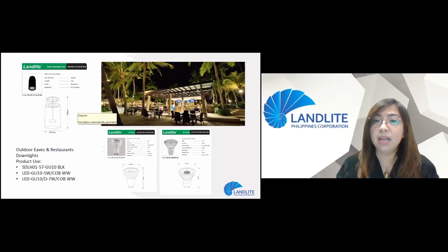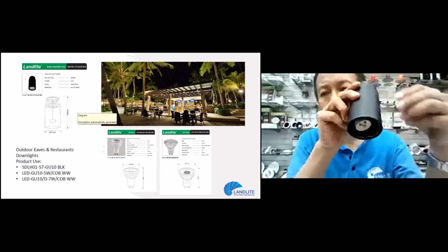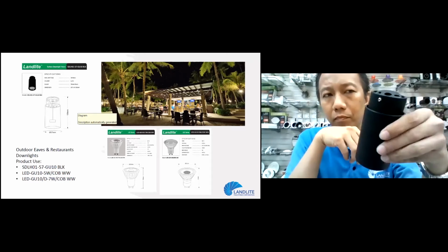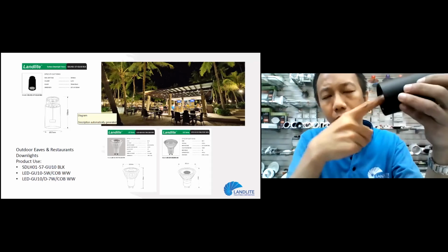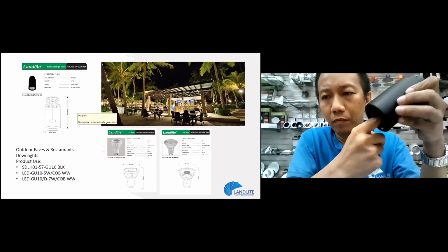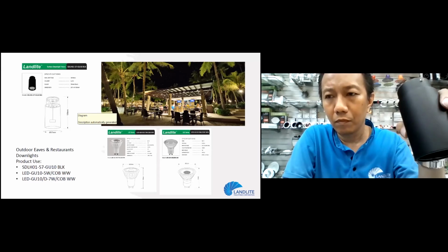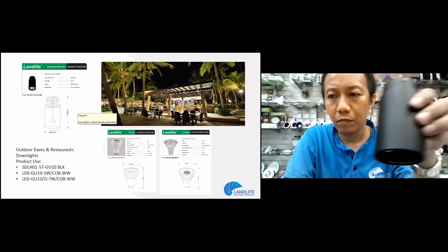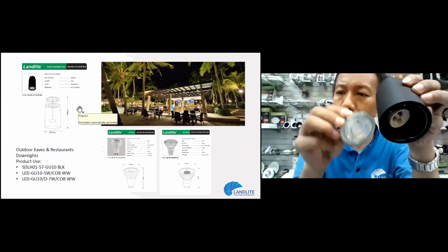Okay, they make sure that they use die-cast aluminum or plastic. Right? Those are the two choices to use. Of course, you can use stainless, but stainless is very expensive. So the next option would be die-cast aluminum. It doesn't rust, right? And then also some plastics. The problem with plastics is that when exposed to the sun, sometimes they crack.